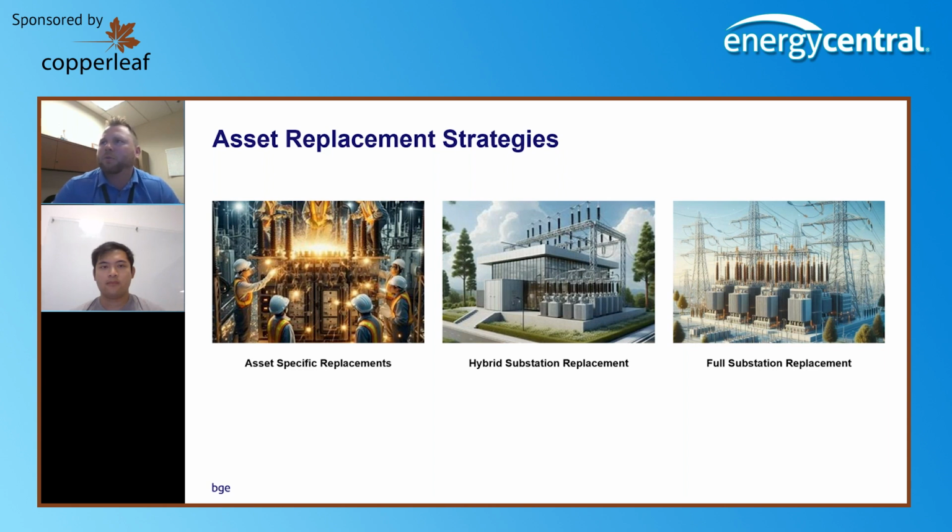Another interesting one that we're exploring is a few substations where we have room in an end of a breaker and a half scheme to build out basically a brand new bay. And so we have 3 OCBs in an existing bay, building out the new bay with vacuum breakers, having all new switches, control cable, new cable out to the feeders. Because it's not in an existing bay, it's like a greenfield site in a brownfield area.